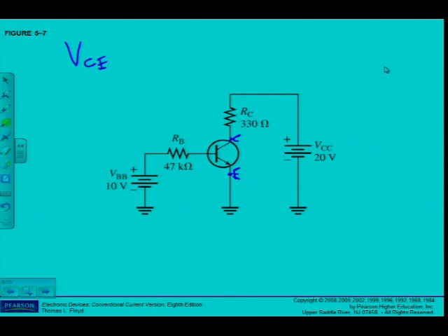If I measure with a single subscript, like VC, I measure with reference to ground. Always with reference to ground. Start reading from the left. I will put my red lead of my multimeter on the collector and my black lead on ground, but you will see that VCE and VC is going to be the same because there's no resistor or anything between the emitter and ground. So in this case, these two values will be the same. Not always true, as we will see a bit later.